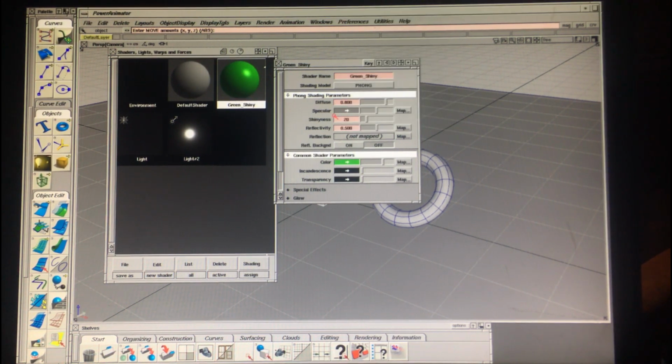It looks pretty good. And then I have the specular. I want the shininess to be very high. You notice when you move the shininess, that highlight gets really small, and we want it, the slider maxes out at 100, but I'm going to go over here and select that. I'm going to go 1000, and it's going to really tighten that. It's going to go super shiny. And we have reflectivity at 0.5, which I just leave, and then there's the specular.